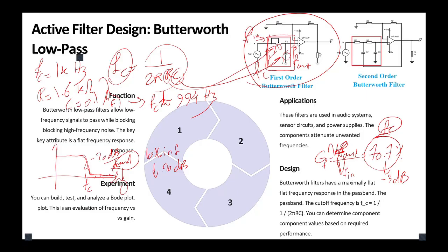And in microcontroller circuits, they are used to clean up the noisy analog inputs from the sensor, so we have more accurate readings. So Butterworth filters are reliable, smooth, and easy to design filters that are used everywhere from music to medication.